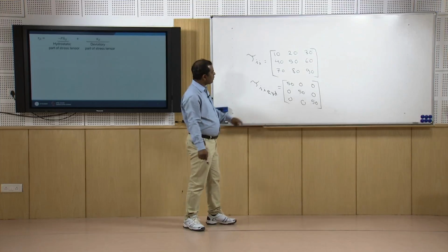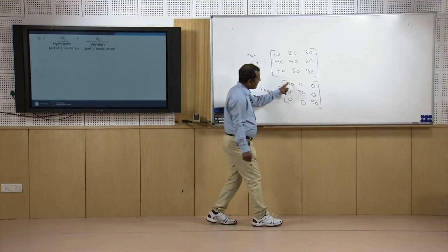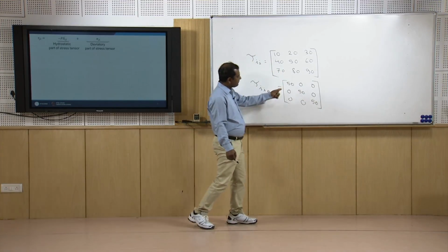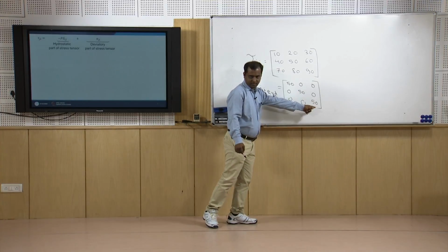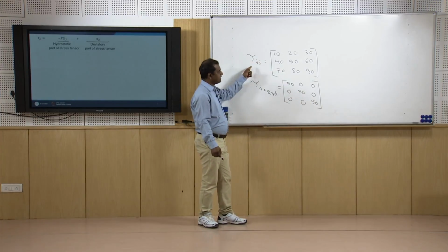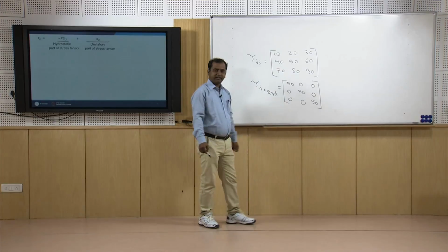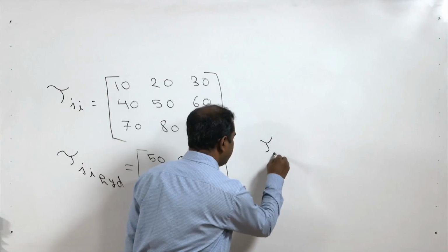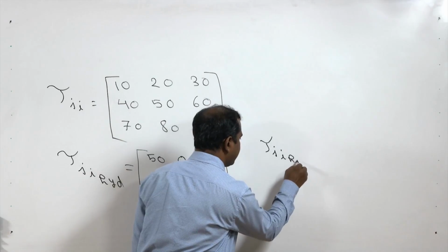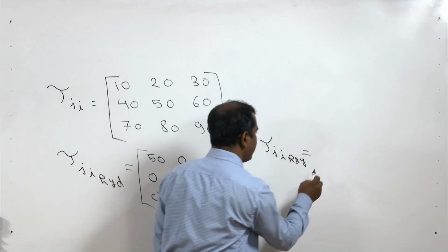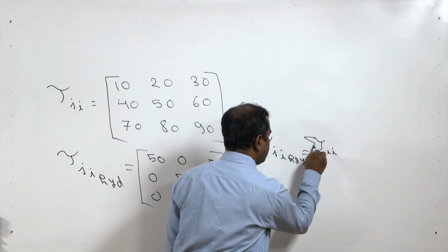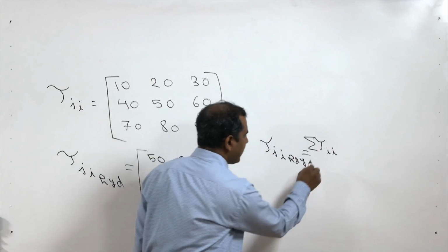Right. So, we have got the hydrostatic part having only the diagonal elements, or we can say wherever i equals j. In this tau ji, only the hydrostatic part exists. So, this tau ji hydrostatic we can write as tau ii for all i's divided by 3.